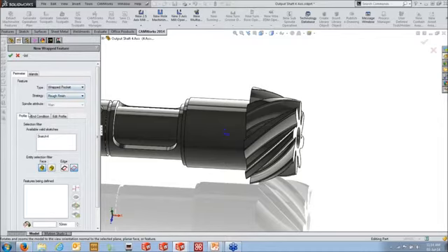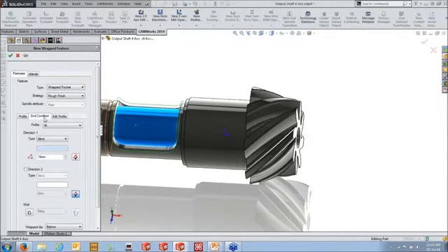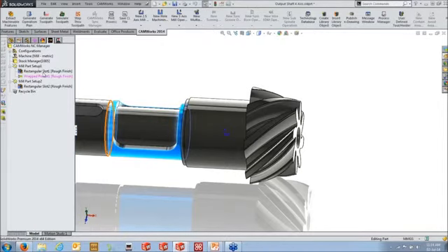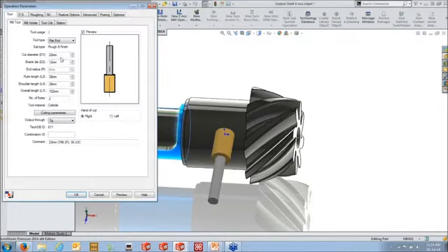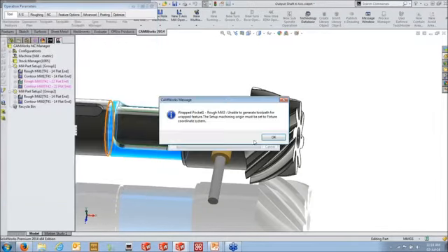We'll just use the wrap pocket option, and we define our profile and end conditions down here. So in this case, I'm going to use my profile to be the bottom face here, and use my end condition to be the upper face right here. And our strategy is still the rough and finish. And notice that it's still going to generate the same operations that we have in our 2.5 axis. You see exactly the same parameters. We just need to change our tool size down to something more appropriate in here. And it warns us here that we need to use the fixture coordinate system in the setup.